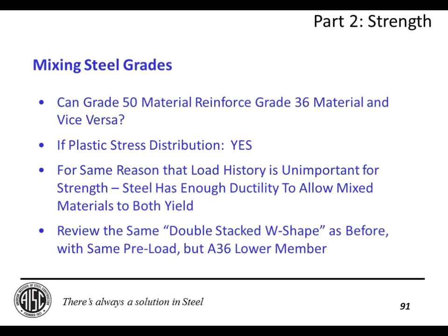So mixing steel grades. Can grade 50 material reinforce grade 36 material and vice versa? And again, the answer is yes, as long as you can assure this plastic stress distribution is valid. And that's for the exact same reason that load history is unimportant for strength. That being that steel has enough ductility to allow mixed materials to both yield.